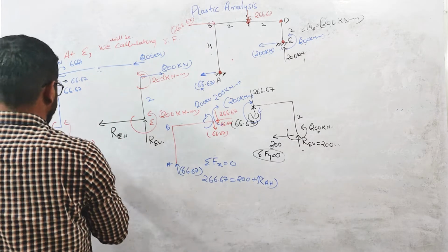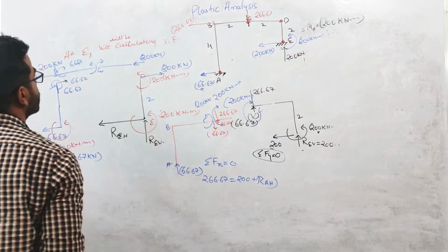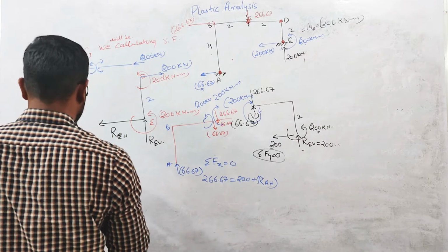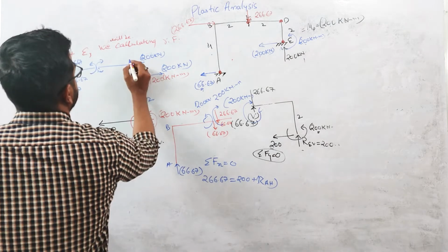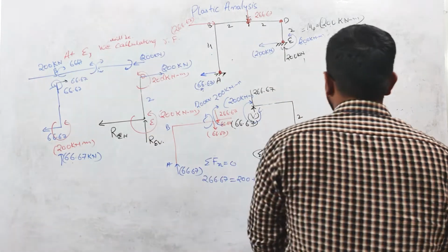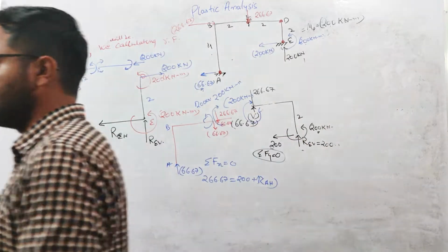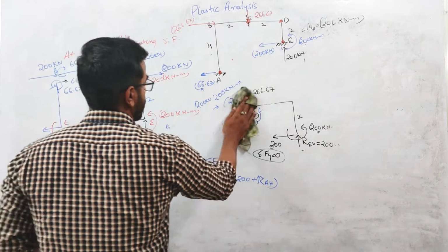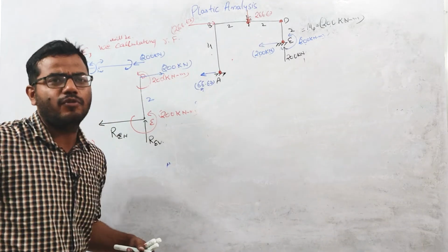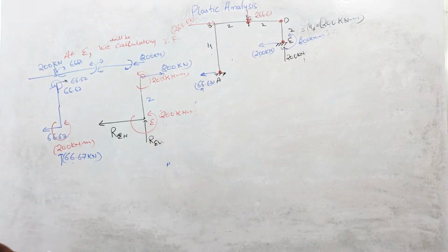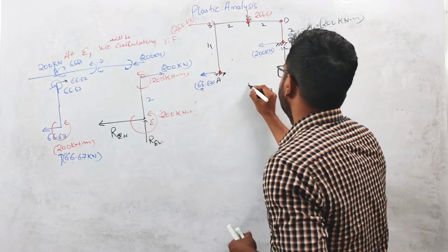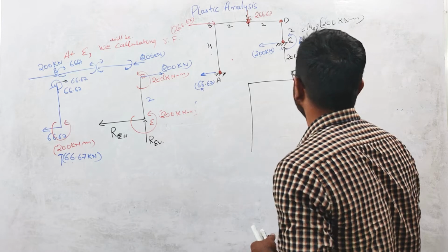At C, the bending moment is looking like this. Okay. If this is anti-clockwise, at D, there will be clockwise. This should be clockwise, right? So if you draw the bending moment diagram, bending moment diagram for these type of structure we have already discussed in slope deflection method in detail. Okay, if you have any doubt, you can refer to those lectures. Okay, so first draw the frame without any support, the simple geometry of frame.